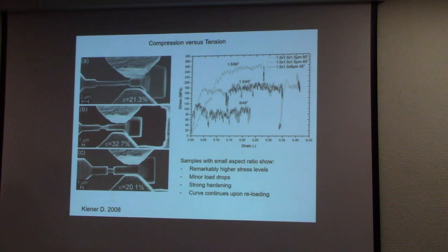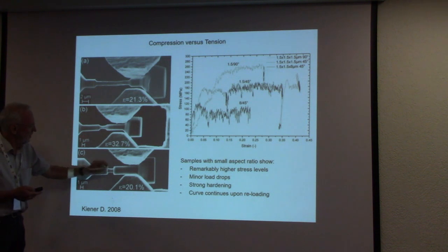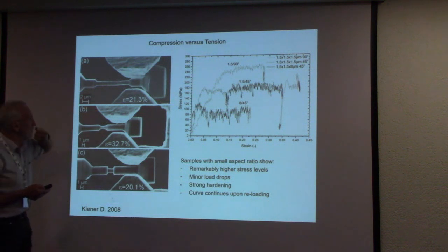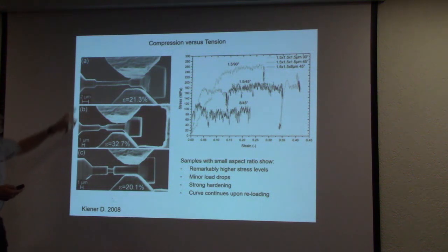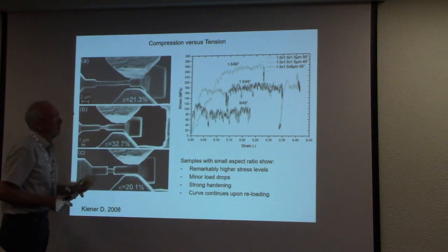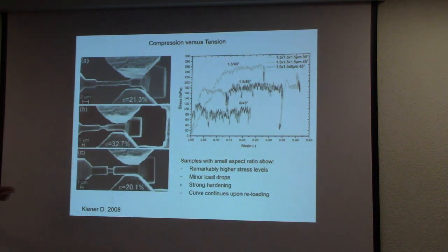Therefore, we started with our tension experiment. It was the first tension experiment. And what we have done now is to simulate this. We have changed the length of our sample, the really necessary deformation length of our sample. We always have the same dimension, okay? And what we can see is that even this volume, the length of it, dramatically affects the yield stress. Nearly a factor of 2, yes? That's enormous.